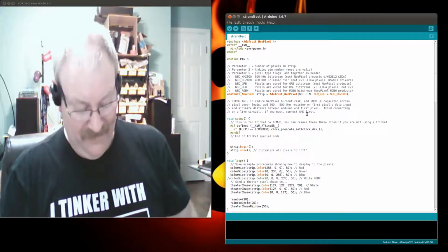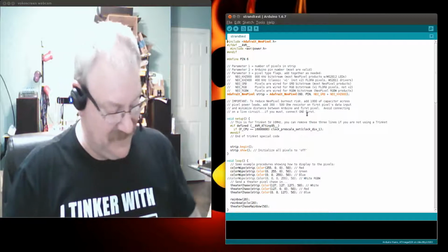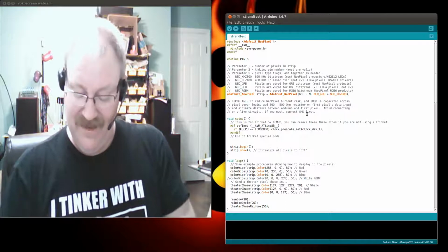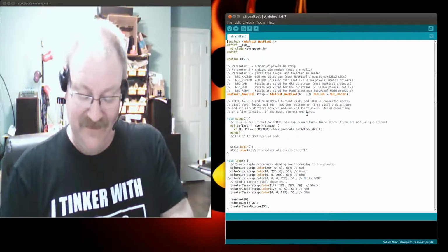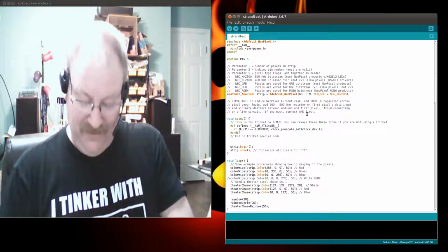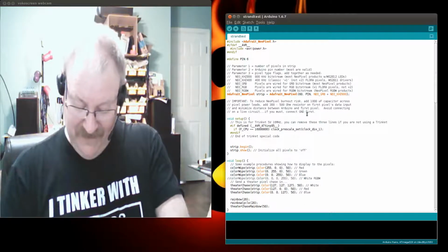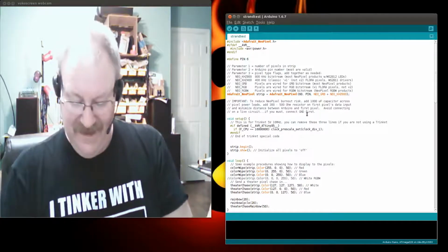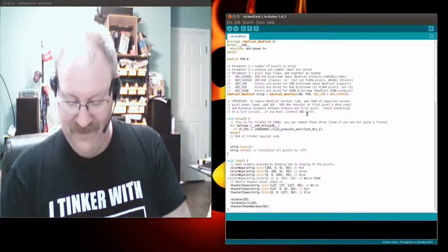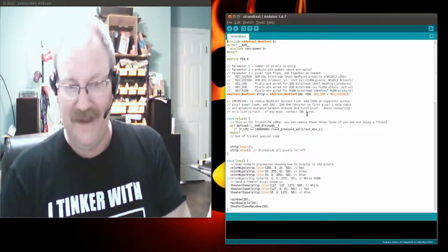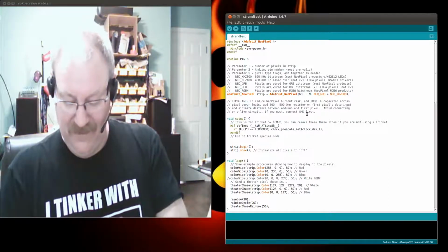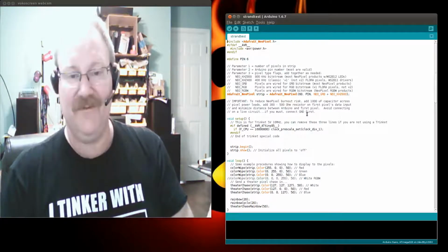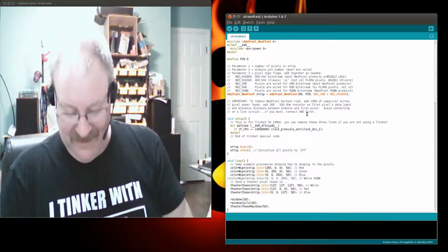Alrighty. Well, the board has a little bit of capacitance, and the Arduino actually has a pretty nice little capacitor on it already, and we're just testing this circuit out. So once you assemble the whole board, you'll see there's a whole bunch of 10 uF capacitors. We use tantalum capacitors that are really, really fast, and the buck converter that's built on this has plenty of capacitance. And so the total capacitance between the buck converter and the 10 microfarad capacitors that are all through the power circuit keep this thing nice and dampened.